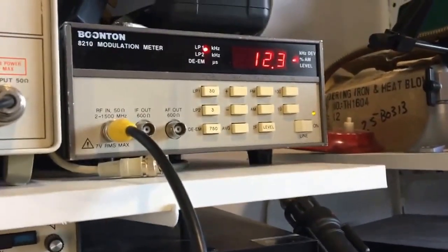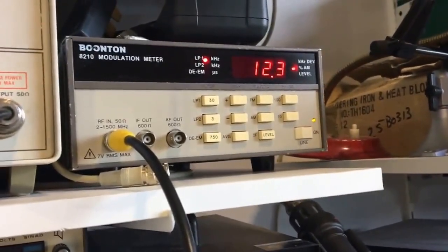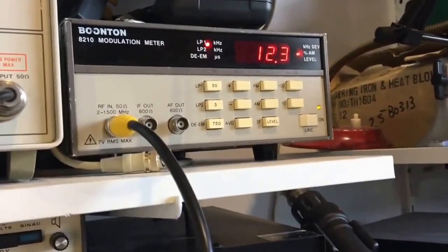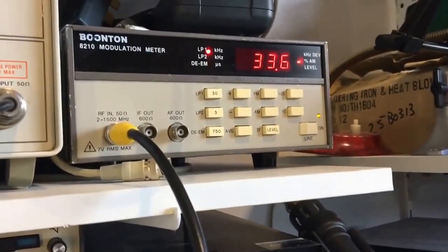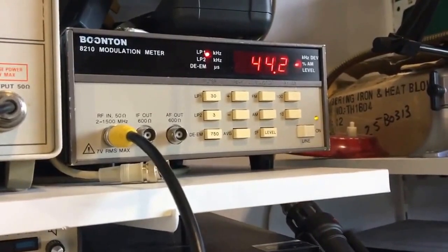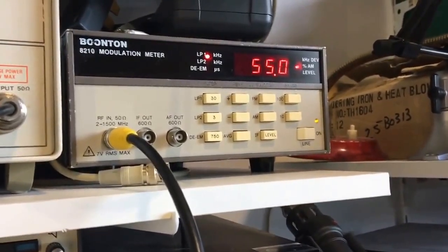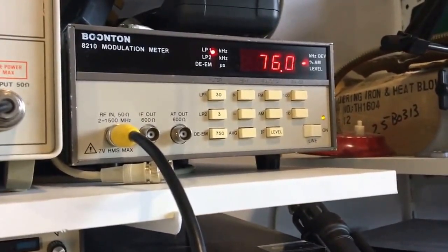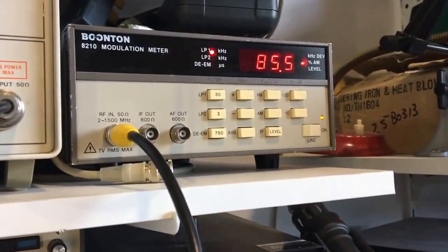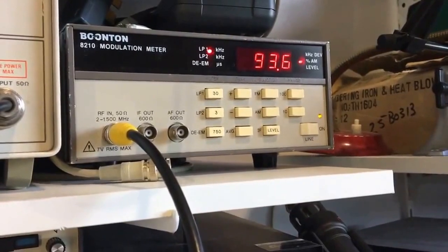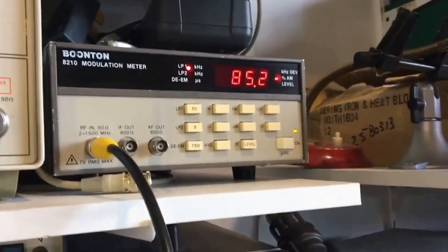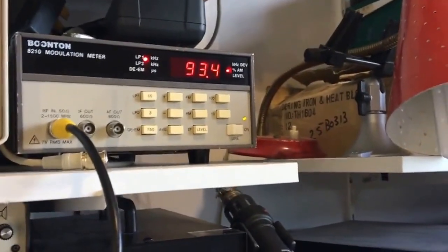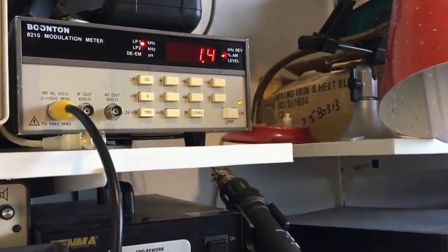Right, so it's not too far off. I mean, I don't know which unit is out of calibration, whether it's my Boonton, which is a bit out, or whether it's the Fluke, which is out. Obviously there's a bit of an error there, but it's not a huge error. I think the worst is 50%, it's out by about 10%. Everything else is slightly better than that. So yeah, it's not too bad. So I'll do FM modulation, turn AM off.